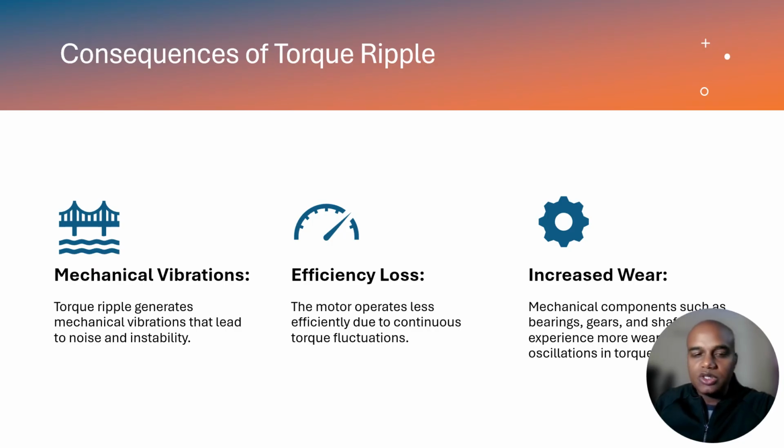And the torque ripple, as you know, can create mechanical vibration. It will also degrade the efficiency of my motor, which is being used for different applications. For example, if I'm using it for an EV and torque ripple is happening, I will feel jerks while running my EV. So this is not a desirable scenario, and it has to be eliminated.